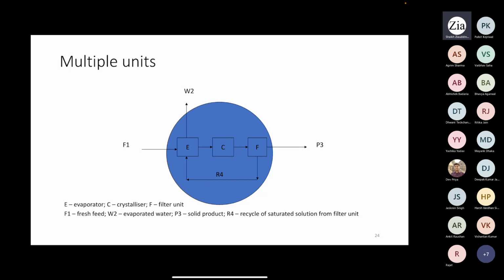And then if you feel that the reactor liquid still has some substrate which can be utilized, you will separate it using either a settler, a continuous centrifuge, or a filter, and then recycle back the residual liquid to the reactor to get a little bit higher productivity or higher utilization of the substrate. And whatever biomass you are getting from the settler or filter or centrifugation system, that you will use in subsequent units. Suppose you need to wash it.